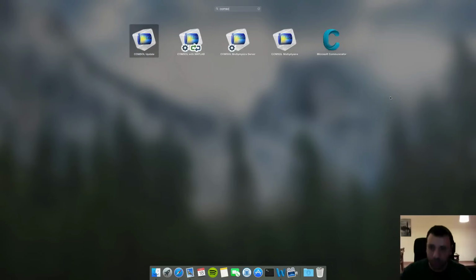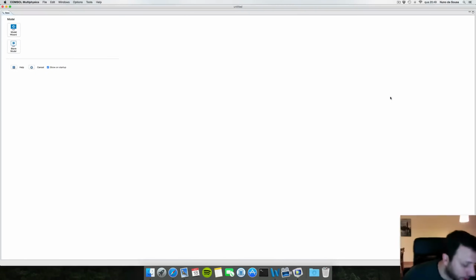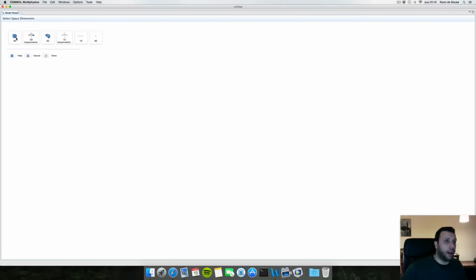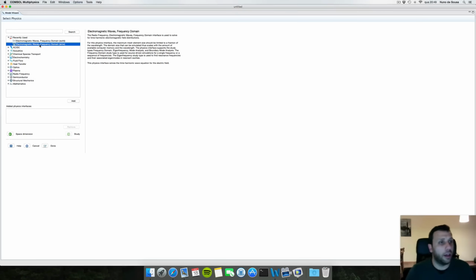Let's open Comsol. And here we are. Comsol 5, last version of Comsol. And we're gonna start by defining the global parameters of our problem. But before this, we're gonna specify our problem. We start by 3D system. We're going to work in a 3D system, and we're going to work with electromagnetic waves at frequency domain.